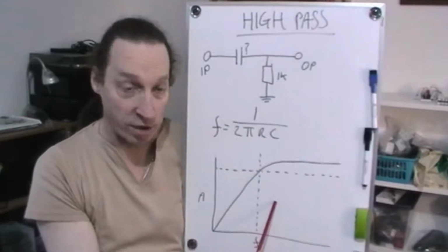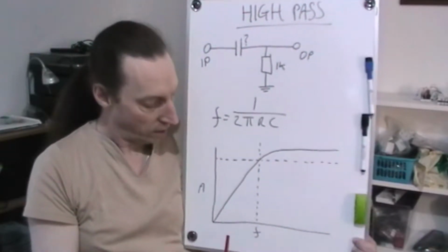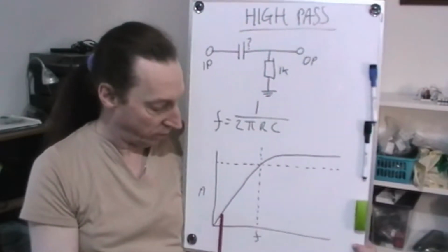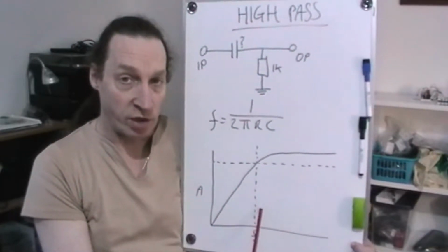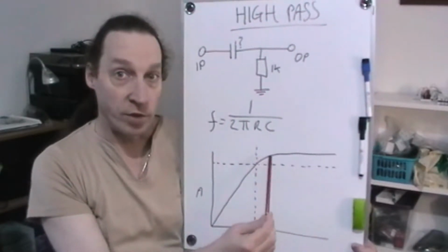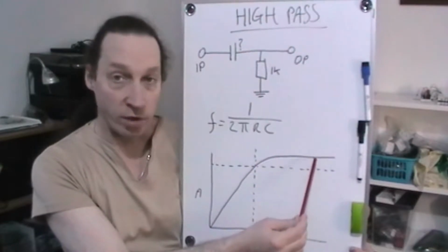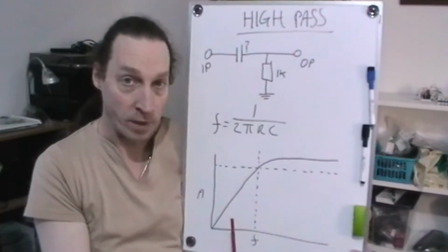Now then, I've drawn a little chart just to show what I'm expecting to get. Frequency against amplitude. So that would be my cutoff point. At my cutoff point, I'm expecting that I will get all of the signal come through above that frequency, and anything below it will be attenuated.